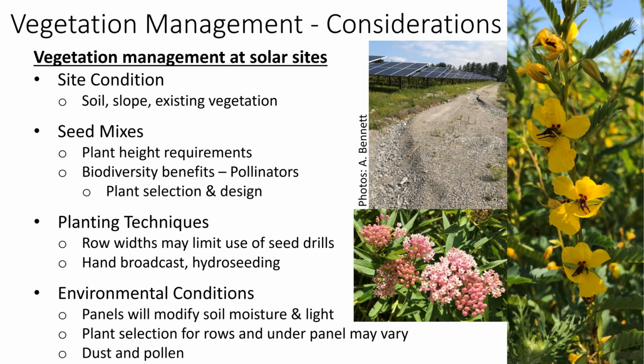So you may want to consider using different seed mixes under the panels versus in the rows. If you did not select to use any vegetation at the site and you're in more arid regions of the country, dust may become a problem at your site. And I've also been asked the question, okay, well, if I do use a pollinator mix and we have a lot of flowers, is that pollen from the plants actually going to accumulate on my panels? And I don't think we have a good answer for that question yet.